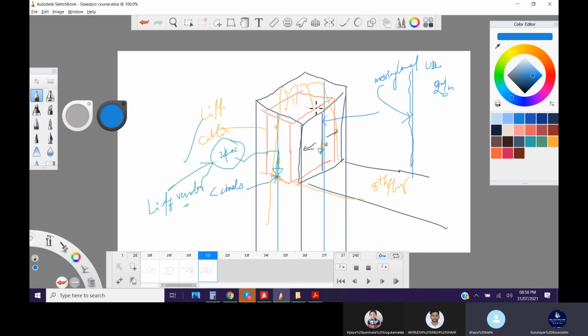But this channel will transfer that moving load to the concrete wall. Why is a concrete wall required? I think we explained this in our practical structural design, manual design, and in several places in the ETABS course also: equipment-carrying structures always have vibration in the X, Y, Z and vertical directions.